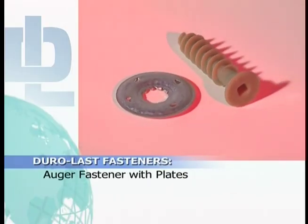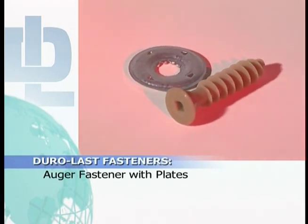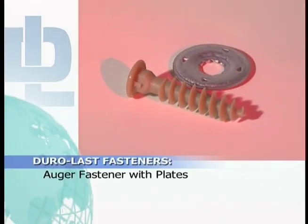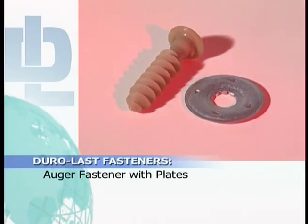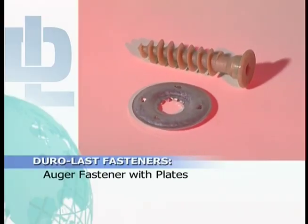The Duro-Last auger fastener with plates is the only fastener that Duro-Last supplies that comes with its own distribution plate. Use this on cementitious wood fiber decks, tectum, gypsum decks, and lightweight concrete decks. The Duro-Last auger fastener is made from glass-filled nylon with an internal square drive.